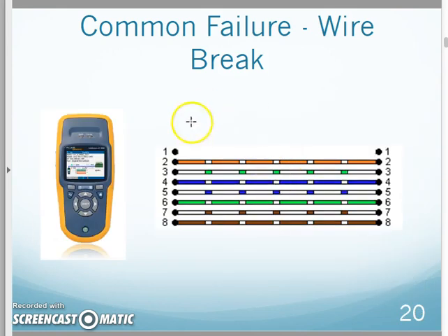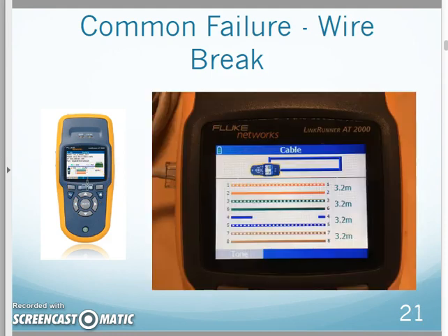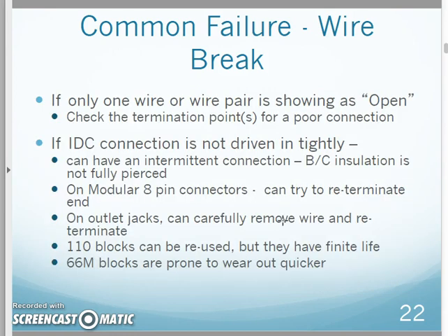And again, that's a clue to be checking, in this case, the white-blue wire pair to see what particular issue I might be having. And again, here's my wire map for my open, and here's my wire mapping meter trying to show me that. And here's actually the one we have in the lab showing you, in this case, pin 4 or wire 4 is not connected. So I would check a little bit closer to find out what's going on.